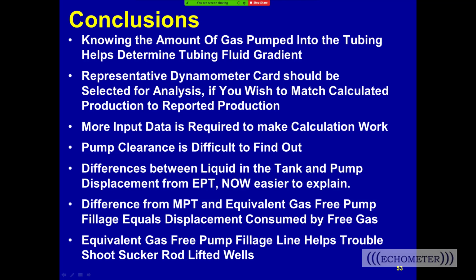Right. I have another question, probably with a quick answer. Is the pump clearance of one side, for example, heavy oil in Kuwait uses 10 thousandths of an inch, so the clearance equation is 0.01, right? The answer would be right. So if you have 10 thousandths in Kuwait, then it's 0.01 for the pump clearance. So that's the OD of the plunger subtracted from the ID of the barrel.